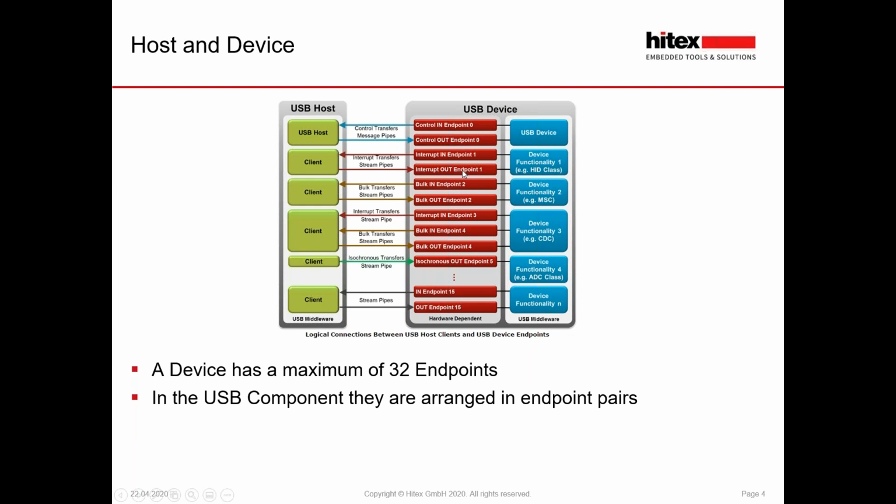This endpoint serves as a buffer to receive data, and then it will generate an interrupt so that you can read the data. So basically, we have a USB peripheral, usually a block of associated RAM, which we then divide up into these various pipes. And these are either into the host or out to the device.